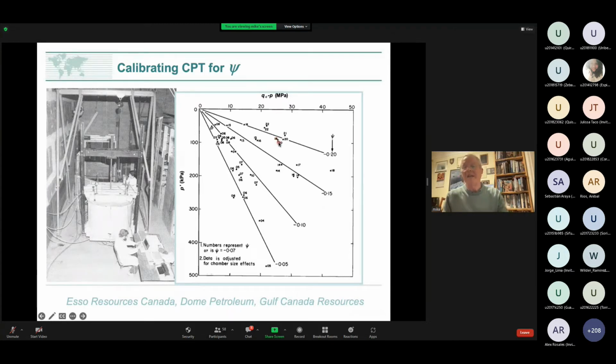These numbers on here: we can take the void ratio of the tank, and we have done triaxial testing to define the critical state locus of that sand. And we can then say, well, we know the critical state locus, and we know the p-dash, and we know the void ratio. We can actually calculate the state parameter. And for sake of simplicity, we've left off the minus sign. So that 0.21 means that test had a state parameter of minus 0.21.